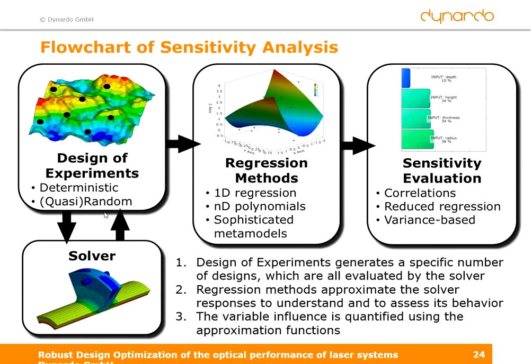So this is a flowchart of the sensitivity analysis. The heart of it is this design of experiments, which means you have distributed your designs in your design space in a particular way, usually homogeneously. And based on this design of experiments, you can now calculate these inputs by the solver, which is here VirtualLab, to get your output.